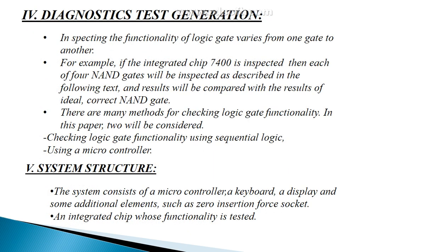Number four is diagnostic test generation. In this, we have discussed that inspecting the function of logic gates varies from one gate to another. For example, if the integrated chip 7400 is inspected, then each of the four NAND gates will be inspected as described in the following test. The link of the research paper has been given in the description, and the result will be compared with the result of ideal correct NAND gates.